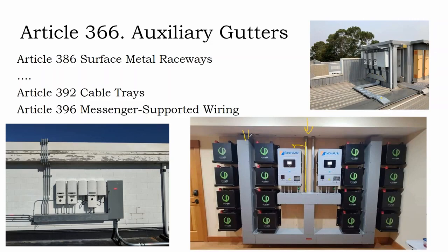But if you didn't have these gutters, you would be running conduit down and looping it around on the wall in big loops, and then you might have multiple conduit runs. So over here on the left, we have 4 EMT runs up to this section of the rooftop, and we have 4 EMT sections running off onto that section of the rooftop.